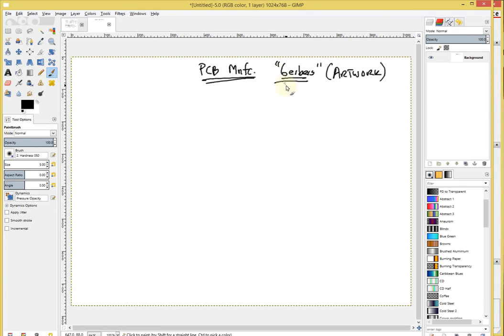When we're working with Gerber formats, there are usually two predominant formats. In the past, there used to be Gerber format RS274D. Every layer from your PCB board needed to be of this format, and in addition to however many layers you generated, you also needed to provide an NC drill file containing the location of the holes and their sizes. You also needed to include something called an aperture list. This could be top layer, bottom layer, copper layer, silkscreen layers, solder mask layers, and a board outline, for example. So you have several files, one for each layer of this format. In addition, you would have an NC drill file, and you would provide an aperture list.